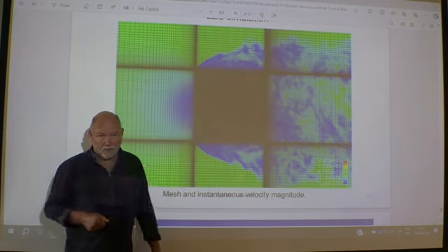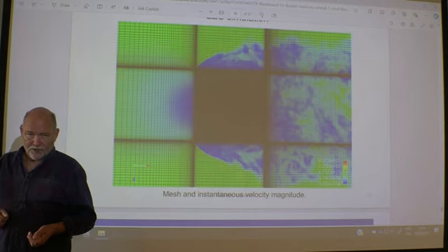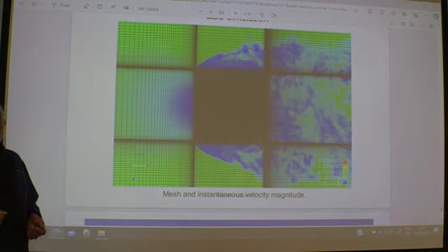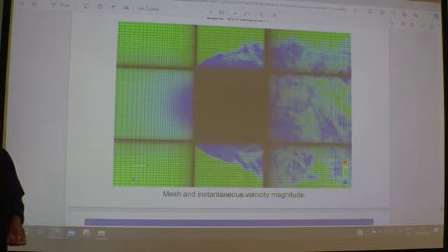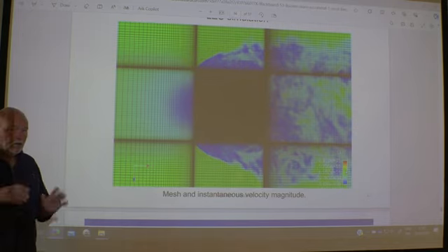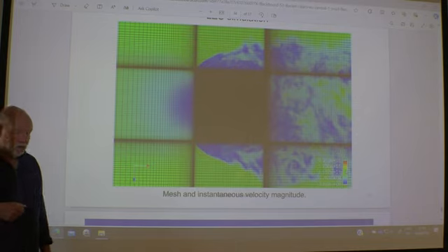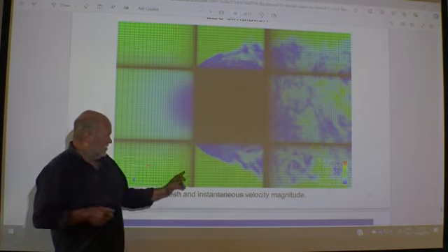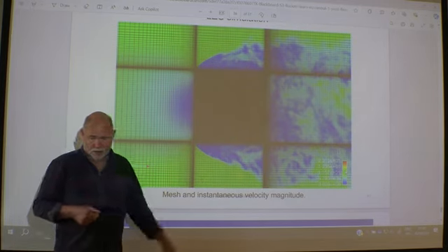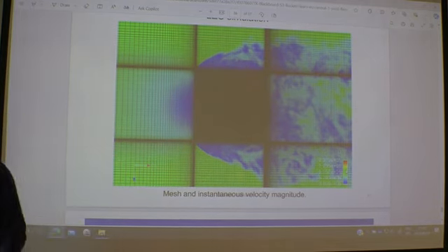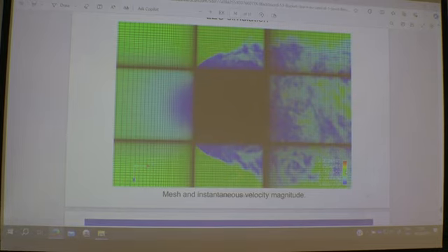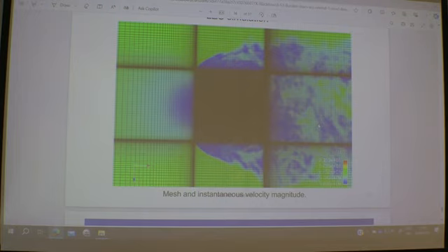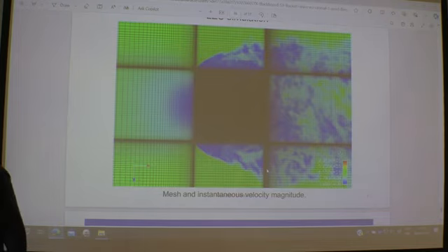Oh, that's going to be expensive if you're running a transient simulation, because you have something called a Courant number, and the Courant number should actually be smaller than 1 in an ideal world. So here you're running into trouble. You have to use very, very small time steps. But with a large eddy simulation, you have to use a small time step anyway. But such a mesh for a RANS simulation, I won't recommend it. At least not a transient simulation.